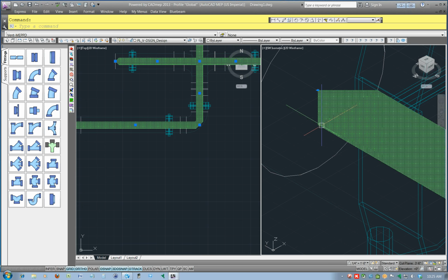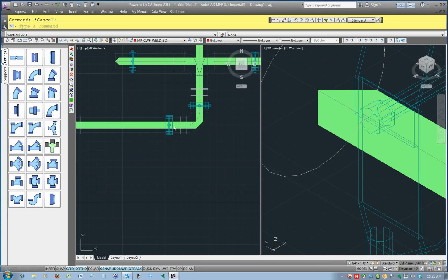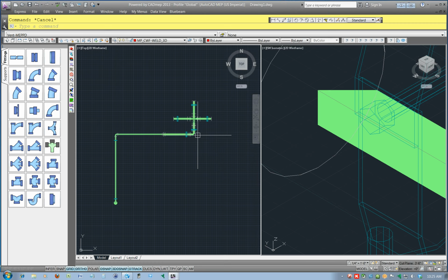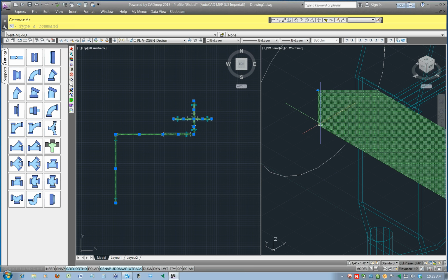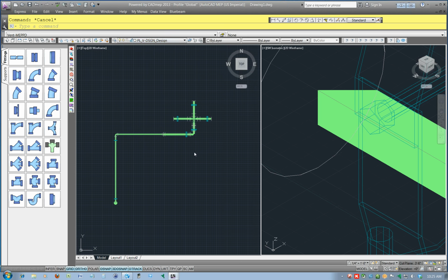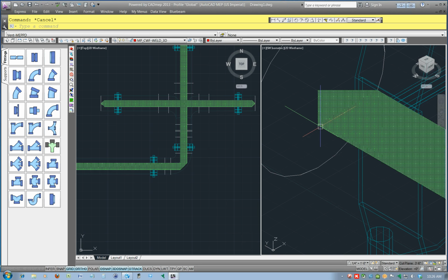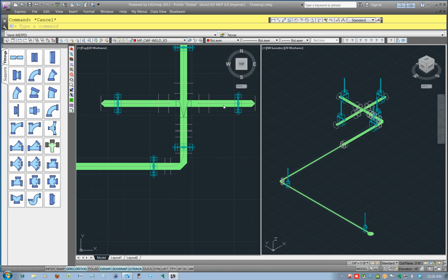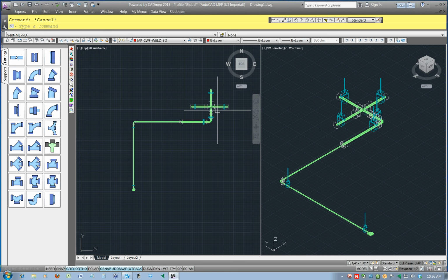Well, it depends what you're doing. If you're doing duct work, where most things are flat or 45s or 90s, and you don't have pitch, I would probably leave my design line on the drawing and just turn the layer off or make the layer invisible. Right. That's what I'm saying. Okay. So it is on its own layer. Yeah. P-vent, design. Yeah, and then you just leave it on and turn it back on when you're working it. Right. When you're doing pitch pipe, design line, it's helpful when you're doing it in the beginning.